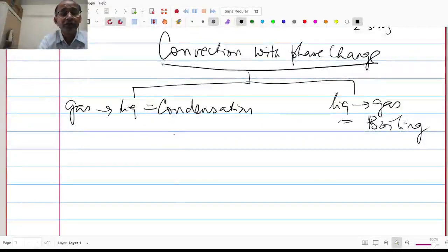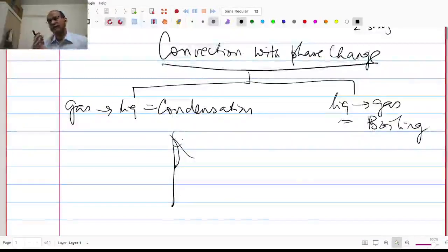angle of wetting. So suppose I have a vertical plate on which a droplet condenses, the droplet would just spread itself. So if I look at the angle of contact, it will be an acute angle. So when that happens, every droplet that condenses on the surface of the solid will wet the solid surface and form a film on it. So suppose there is one droplet that condensed here, there is another droplet that condensed here, there is another droplet. Basically all droplets don't have their own identity, but they just merge with each other by spreading on the solid surface. So you then start getting a film.